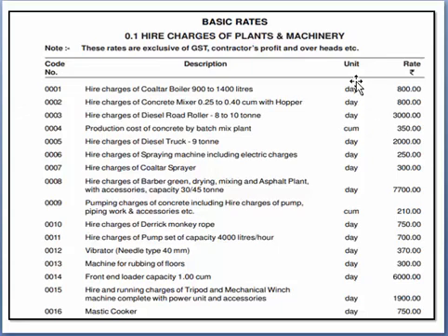So what is this unit day? You will have the question in your mind about why the day is written. So students, basically when we hire any labor or machinery for the construction site, the unit is considered as 1 day. These rates are given for 1 day, and the day includes 8 hours. The day doesn't mean 24 hours.